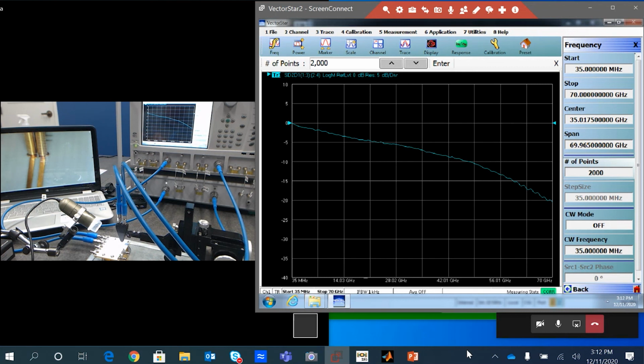And in order to verify they are or not, we have a camera here that's showing the probe tips. It expands it on the display, as you can see here by the display on the PC. So those are the two signal pins within the probe itself. As you can see, there is no ground. So we have no common mode path, just a differential path with crosstalk. And they're making contact with the differential line, as you can see on the trace.